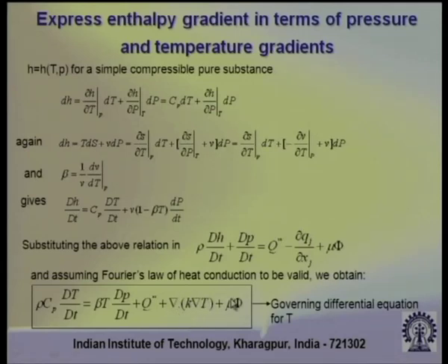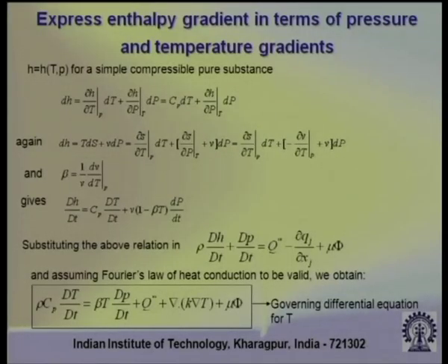And this is the viscous dissipation term. In many problems in heat transfer, because of low velocity gradients, the viscous dissipation term is neglected, and if compressibility effects are not important, then the volumetric dilation term is also neglected. So on the right hand side you are commonly left with the heat conduction term and the heat generation term per unit volume. So we have seen the energy equation as a specific example of a conservation equation. How many conservation equations have we seen? We have seen three different conservation equations: the continuity equation, the momentum equation and the energy equation.